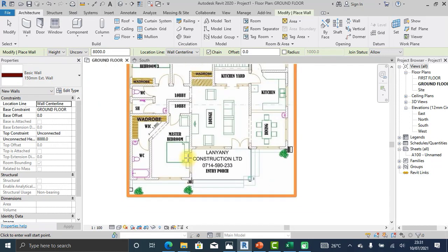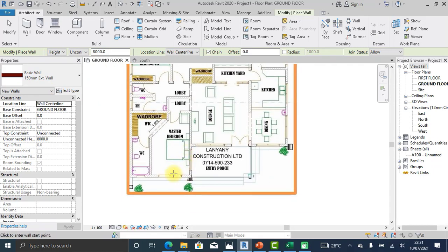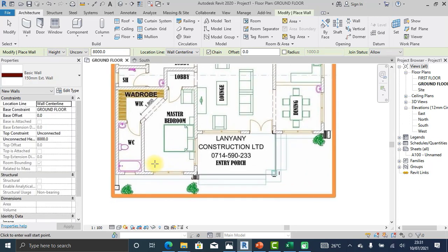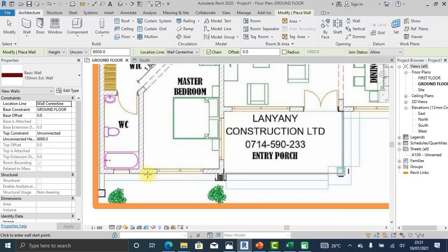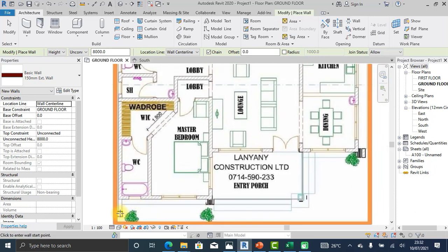So we come here in drawing walls in Revit Architecture. For instance, since we are already using a design plan from this image, you do not need to leave openings. Draw walls across all openings, and then the doors and the windows have a way they can create their own openings in the walls as soon as you place them. So that means I have to really draw. Now my justification here, let's say, is on the center line.